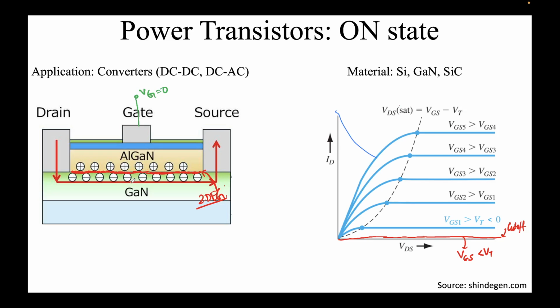And again, there's some compliance limit. So all those numbers, when you say it ceases to exist, it never happens. It's just that its concentration reduces to such a low number that the current is very small. It's the leakage current only, which I have drawn in red here. Okay, so this is the ID, which is below, when we are below the threshold. Okay, in this VDS. Rest, if you are above threshold, you see VGS, let's say, is above threshold.